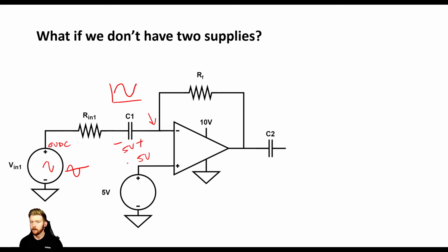Now, there are some unfortunate side effects, namely low frequency response. So if you try and work with a DC signal here, it's just not going to work. Or a low frequency signal, it's not going to work, because these capacitors are going to start working like open circuits and blocking that signal. But this is a nice little solution if you maybe need just a single supply amp, but it does take a little bit more analysis.